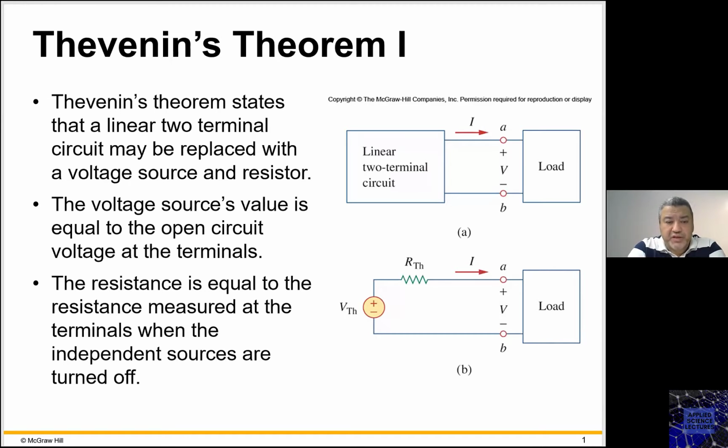So in today's lecture, we will introduce Thevenin's theorem, Norton's theorem, and the concept of maximum power transfer. So what does Thevenin's theorem say? Thevenin's theorem says that if you have a linear two-terminal circuit, made of resistors and sources,